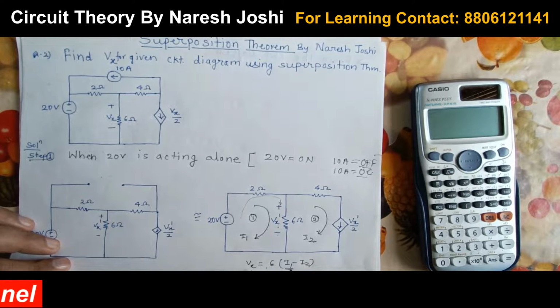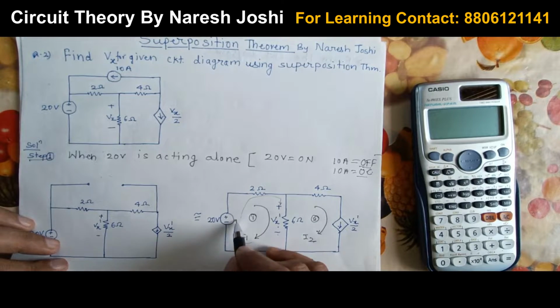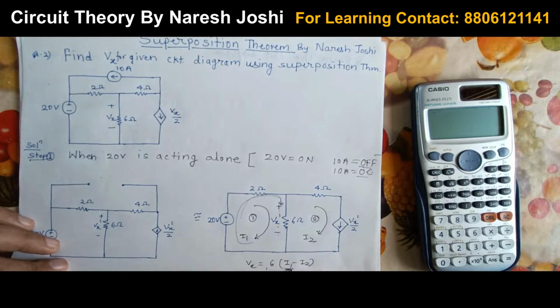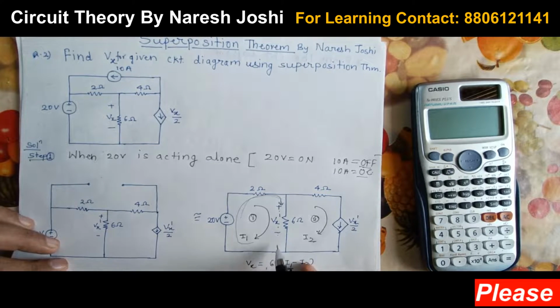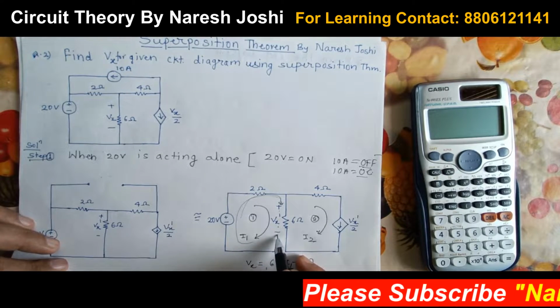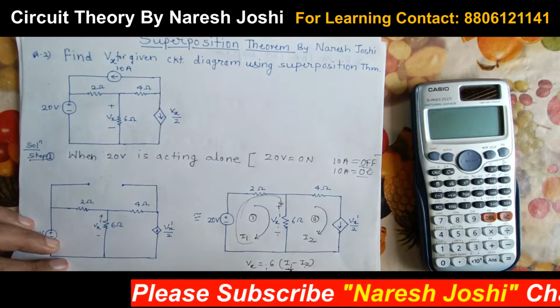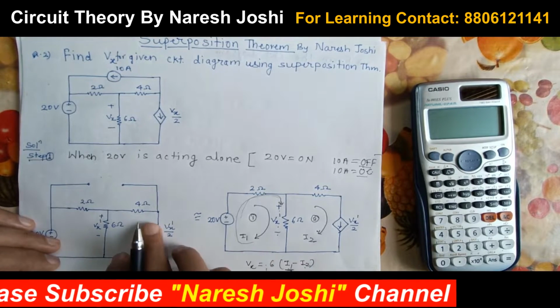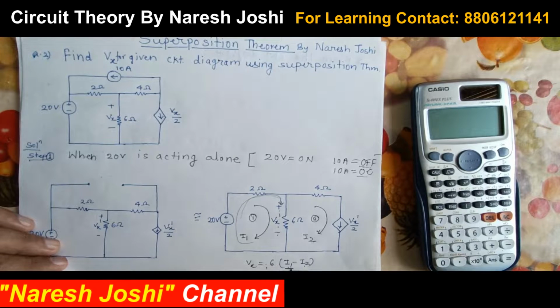This is very important, many students make mistakes here. So always remember, when your current is moving like this, whatever sign is here, that sign you have to consider and you have to write this current first. I1 minus I2. But if you write it this way, it is I2 minus I1 and the first sign is minus, so here we will write the minus. Clear? I hope you understand this. So from the circuit diagram I will write it directly.